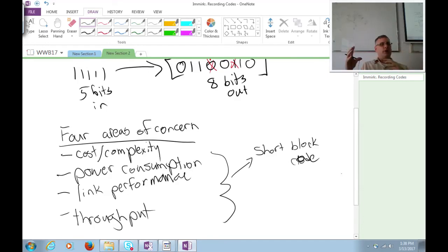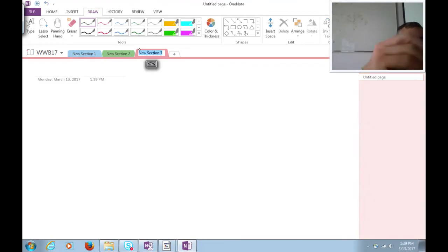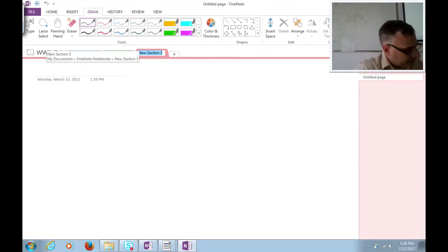Short in that we don't have that many inputs and don't have that many outputs, so the coder can be implemented in some sort of hardwired configuration instead of a table lookup, which in hardware would take tens of thousands of devices to implement. And by block code, we mean it's fairly simple to construct, in that you have a small number of input bits that produce a slightly larger number of coded bits. Then you can make a tag that codes its data very efficiently. Let's explore this idea a little more: how to make a block code.